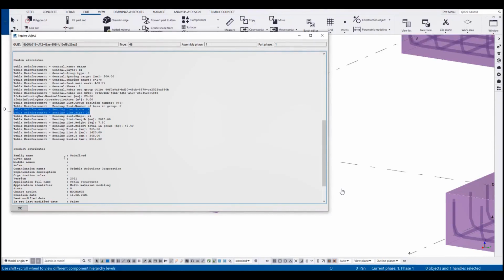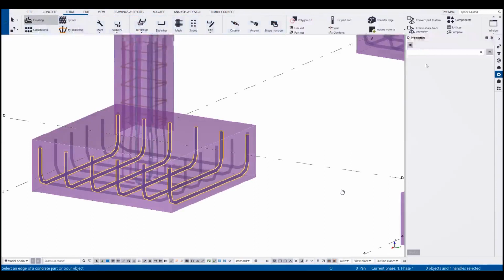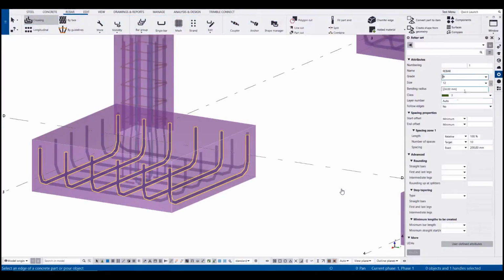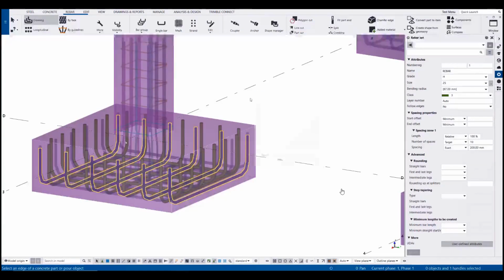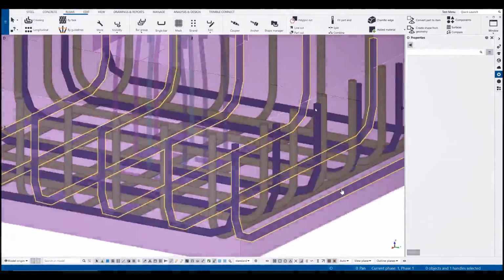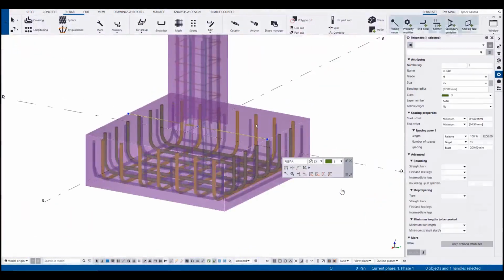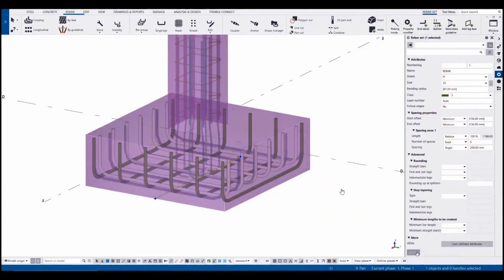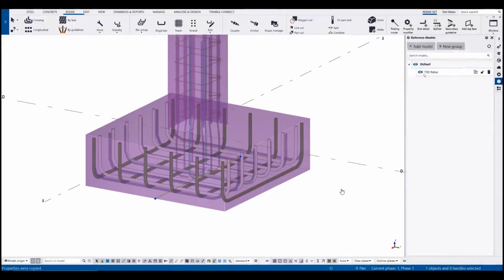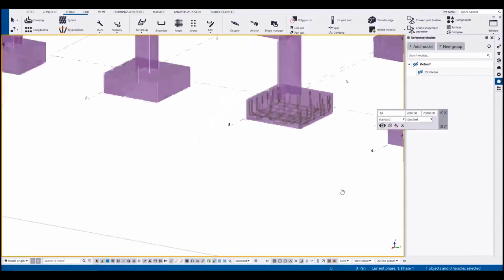All the rebar data can be seen there, if they are required, including the structural designer fabrication information. We're going to use this information to model rebar sets, which are Tekla's native rebars. And we will try to copy and make the rebars in Tekla look the same as the design intent rebars. Here I'm changing the spacing, changing the grade, changing the size, and soon I have the rebars looking exactly the same.